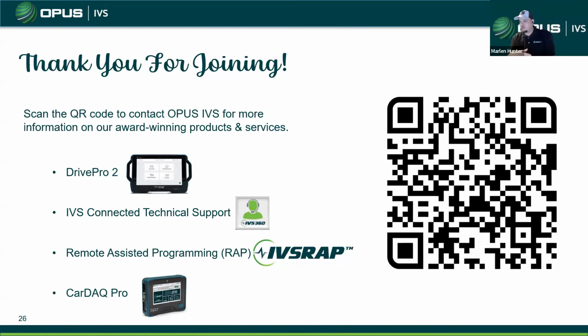Jose asked, do you have a year where the new models are required, or could it be any vehicle? I left it kind of broad. 24, 25 model years, almost all of them for sure. 21, 22, you're starting to see it. But you go into it and look up the radar calibration and see what you have to do from there. That'll show you if it needs to be configured, if it needs an ECU security key, and whatnot.